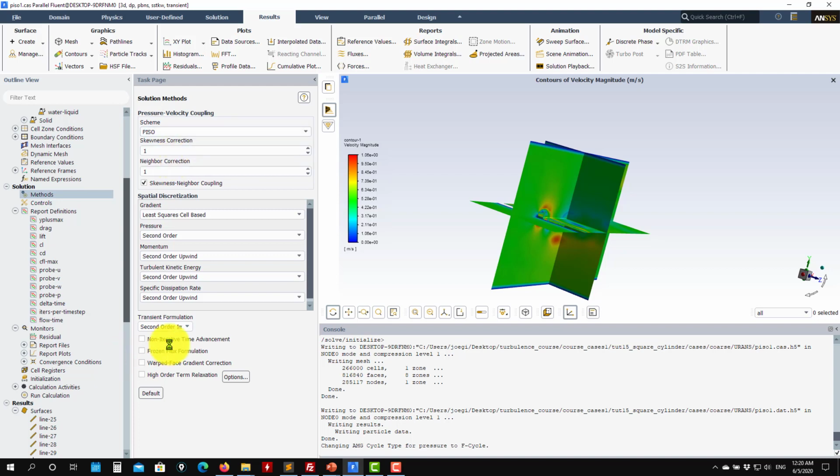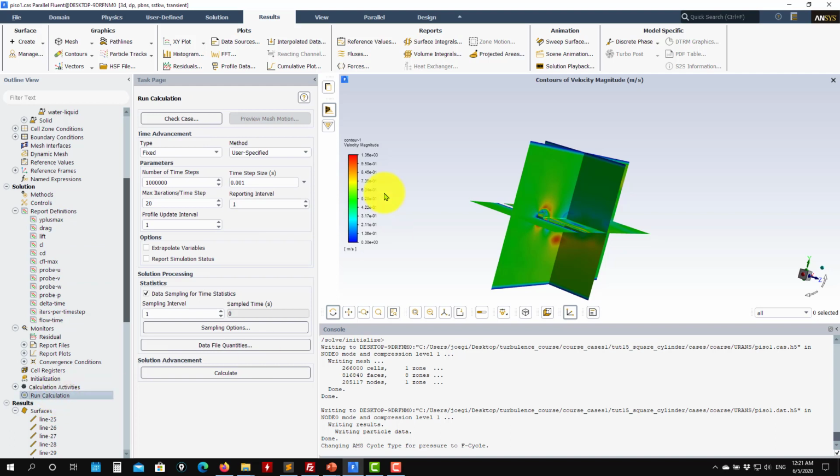You are going to see that. And the NITA in theory is much faster, but you need to be careful that your CFL number must be less than 1 to have good accuracy. Instead, when using the iterative one like this, you can go with a large CFL number, and then by adding sub-iterations, you will guarantee that you converge the solution within every single time step. We're going to see that in action, okay? So we go here, run, and we can start to run.